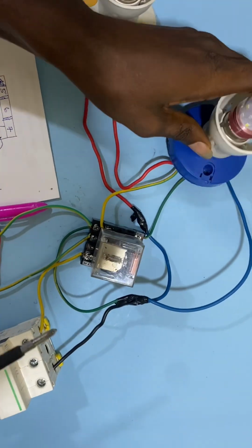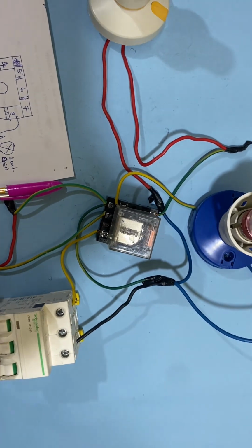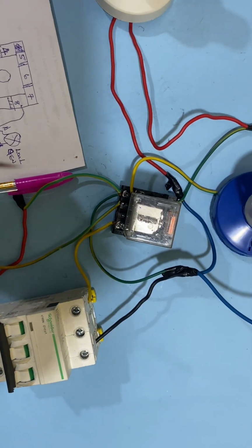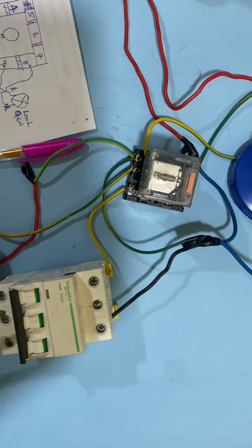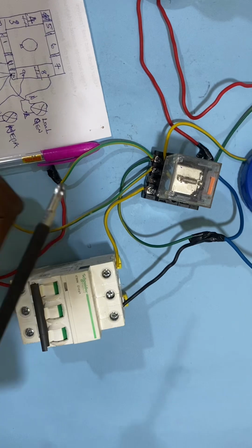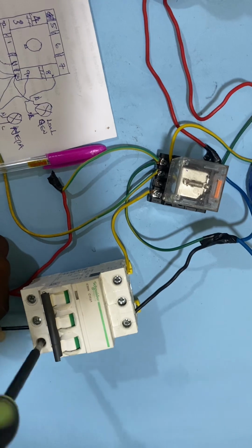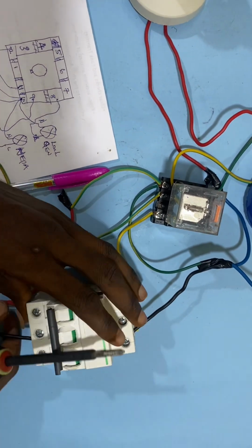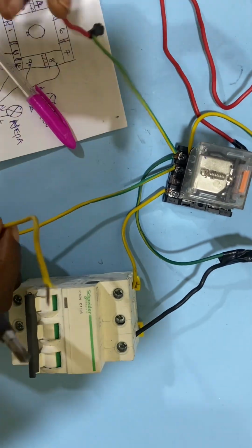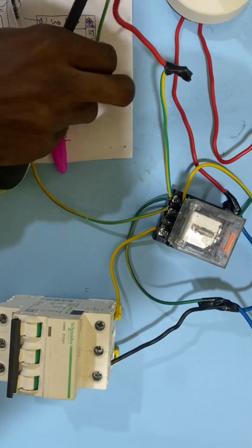Now I'm going to bring a load into the NEPA. So we are going to bring the NEPA load now. Let me bring the table. This is my NEPA supply. So this is my live terminal of the NEPA. Alright, I'm done connecting it. So I'm going to connect the neutral of the NEPA at this point. Right, I'm done with that. So the next thing is for us to power the load. So this is my generator. This is the neutral of my generator, and this is the live of my generator.